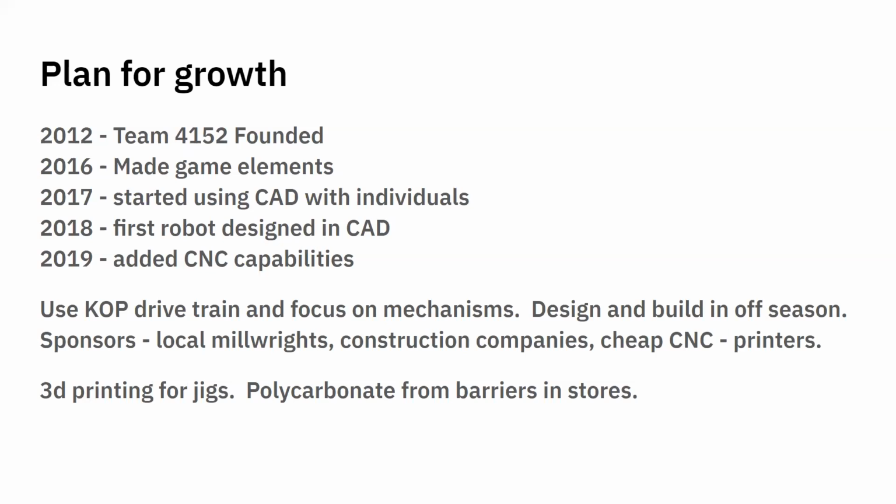The other thing is that, again, if you don't have the capabilities, there's cheap alternatives. So there's the cheap CNC, which is basically just use a printer, print off a sheet of paper with the markings on it, glue it to a piece of material. Now you have an incredibly accurate system for figuring out where to put your holes and things. So there's ways to do it. We 3D print jigs. The key thing that we found is don't use the jigs for drilling. We use a punch so that we put the punch in the hole, hammer it in, and it allows us to easily transfer where we want our holes drilled.